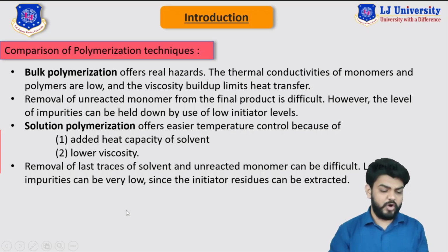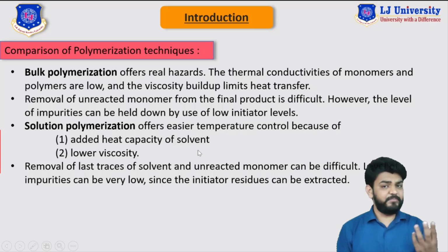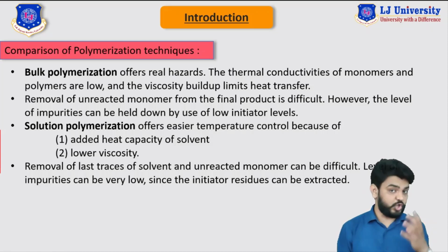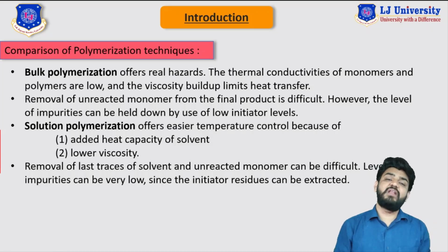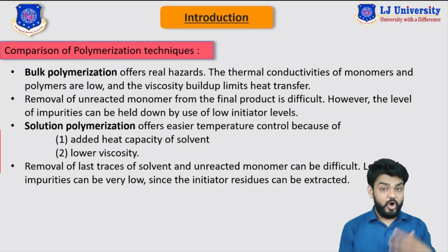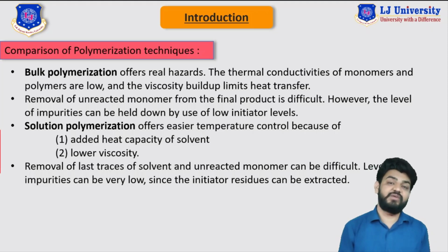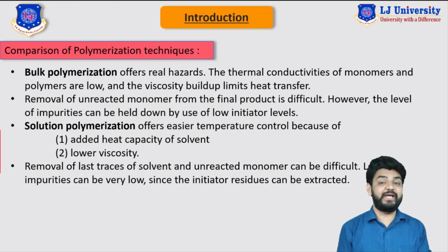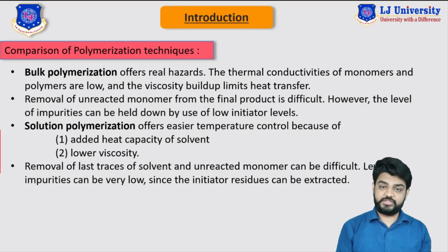This is because of the added heat capacity of the solvent, right? So in the solution polymerization, we are going to use one solvent. So this solvent itself acts as an added heat sink, right? It will also facilitate the heat transfer, and it will have higher heat capacity. And the second reason behind this good thermal control of the solution polymerization is the lower viscosity.